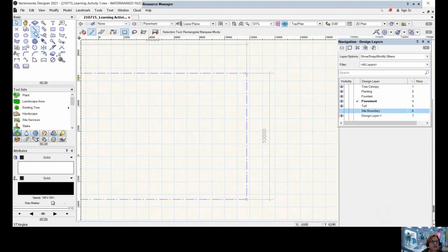To do this, we're going to use the line tool. So go up and click on your line tool. When the top right comes up, click on it. And you'll see if you just drag your mouse anywhere, you're starting to draw a line. Now to make sure that it's actually vertical, it says it's going along the line. You could also hold your shift key down and it shows object/vertical that you're following along a vertical trajectory. So there's a couple of ways of making sure it's vertical. But because we're following the site boundary, Vectorworks is smart enough to know we want to go vertically.